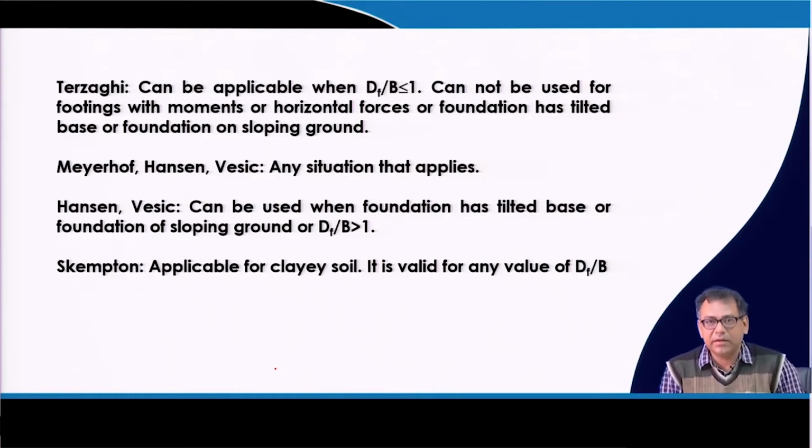So, depending upon your requirement and availability of the values and the conditions, you have to choose the appropriate bearing capacity equation. But in my recommendation, you always use two equations, any two methods always, and then consider the minimum one or the lowest one as your bearing capacity value. So, always it is better to use two equations.